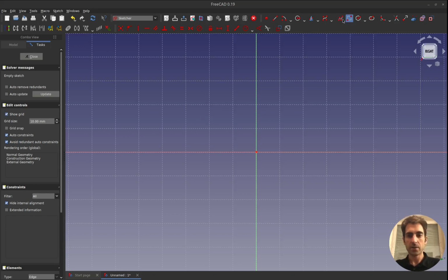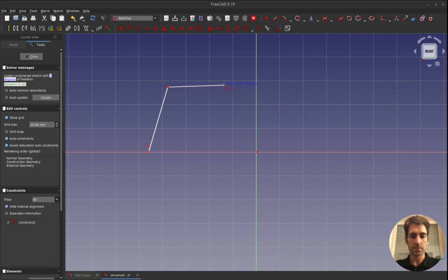And now we are going to use something which is a polyline. So here on top you can see the polyline. If I hit the polyline, I can start doing different points, and technically speaking, between all these points it is creating a line. So that's the polyline. If I slowly go to the vertical, it is also putting a constraint. That's the nice part of having the automatic constraints on the left.